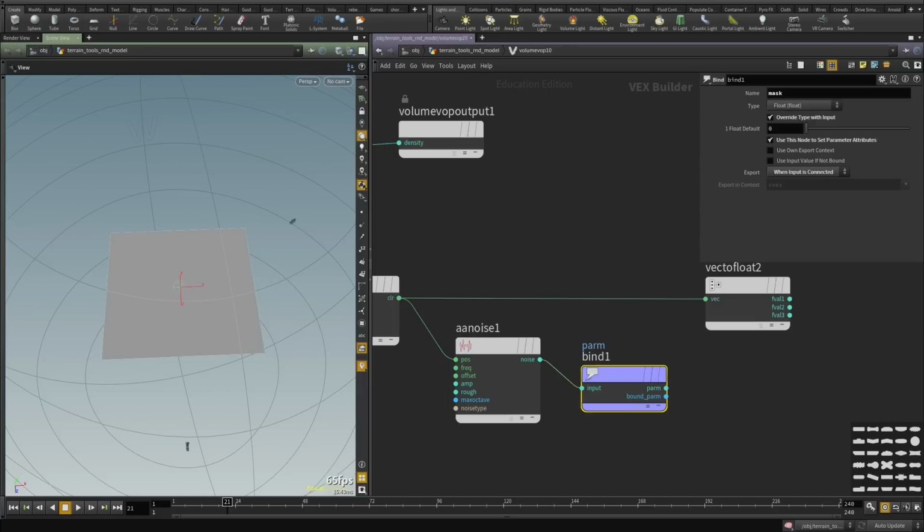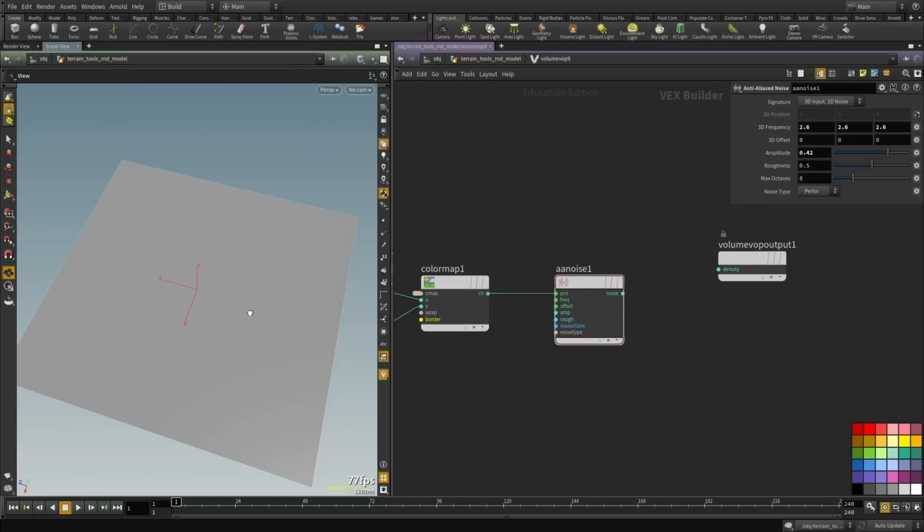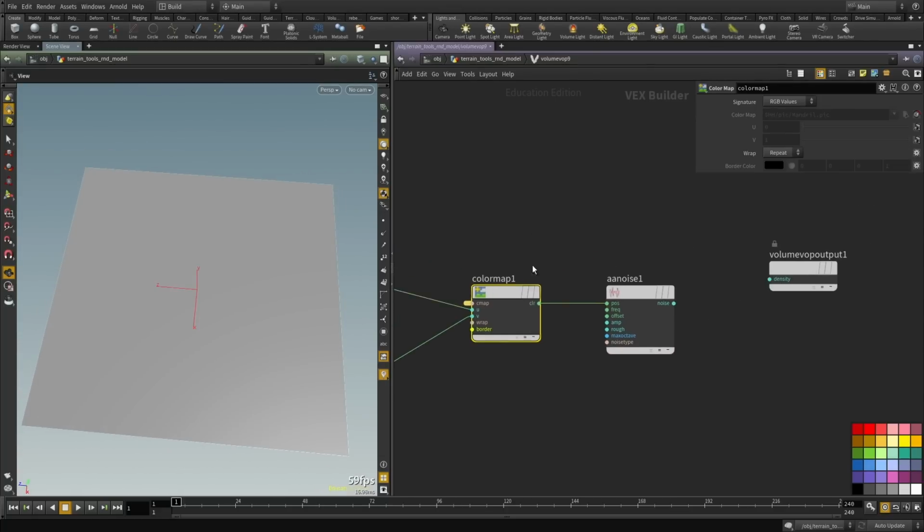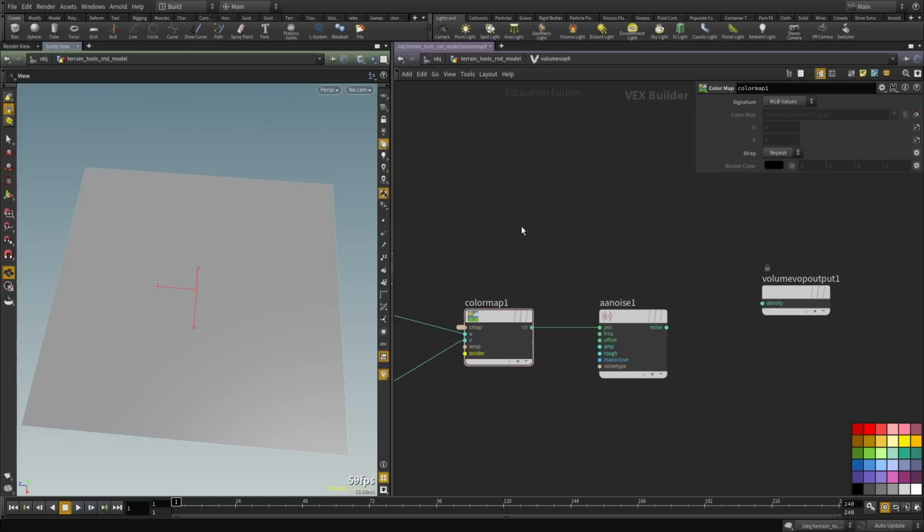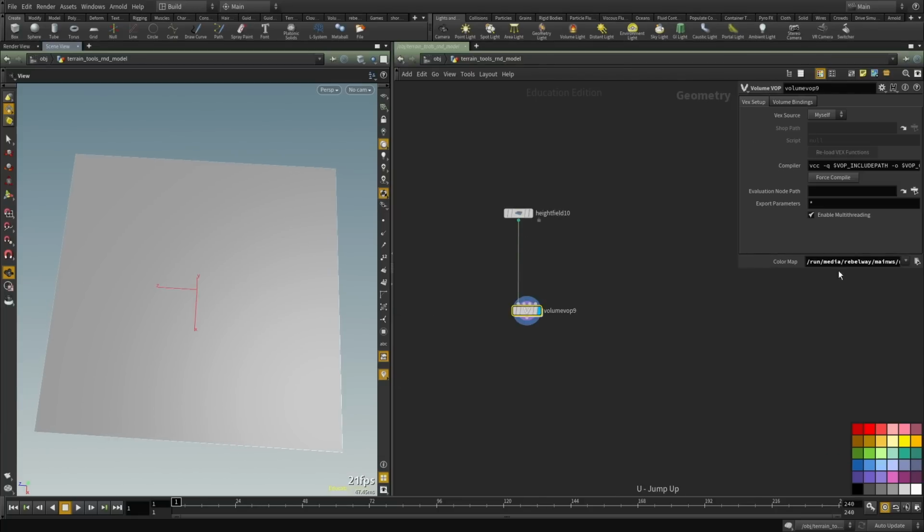So I'm going to save the frame as a RAT file, and I'll restart Houdini and come back. So I fixed the issue, and the problem seemed to be related to the EXR file. And what I've done is I made the 2K version of the image and saved it as a RAT file instead of an EXR. And this is the file I'm using now.